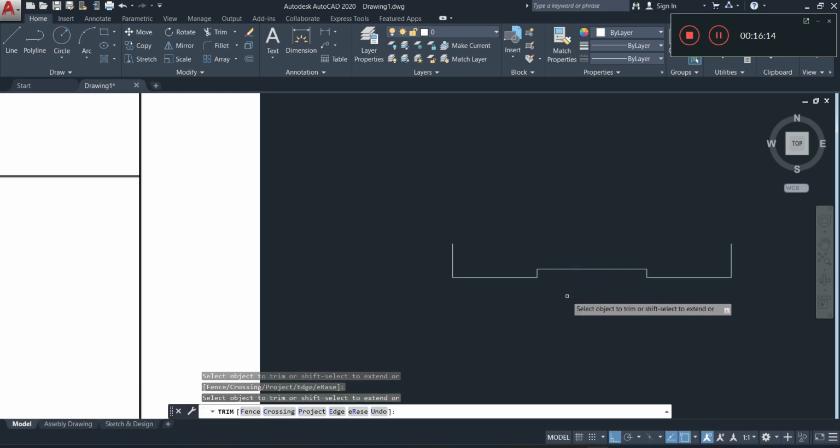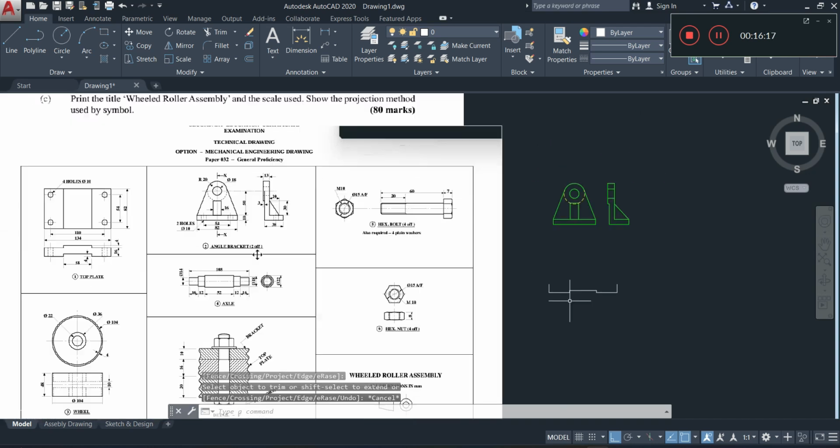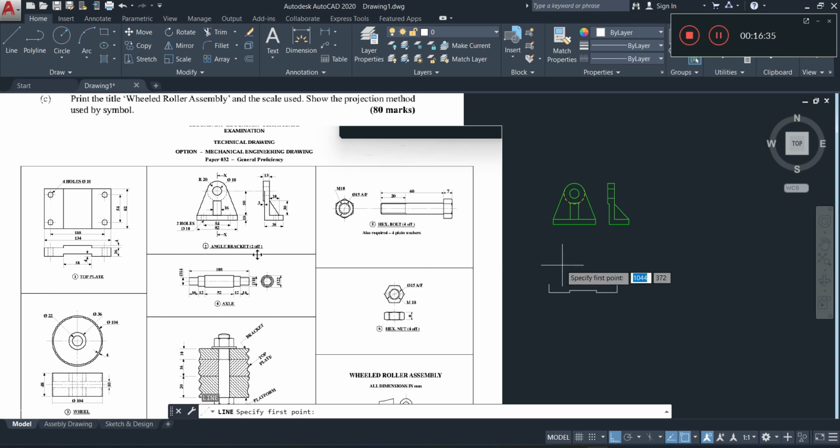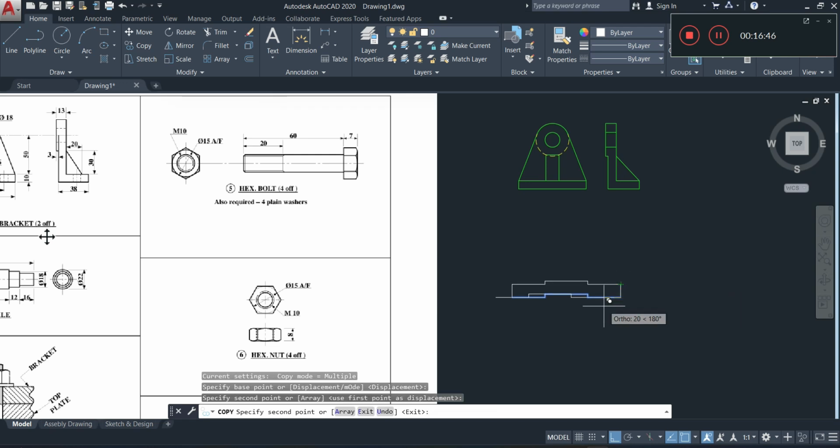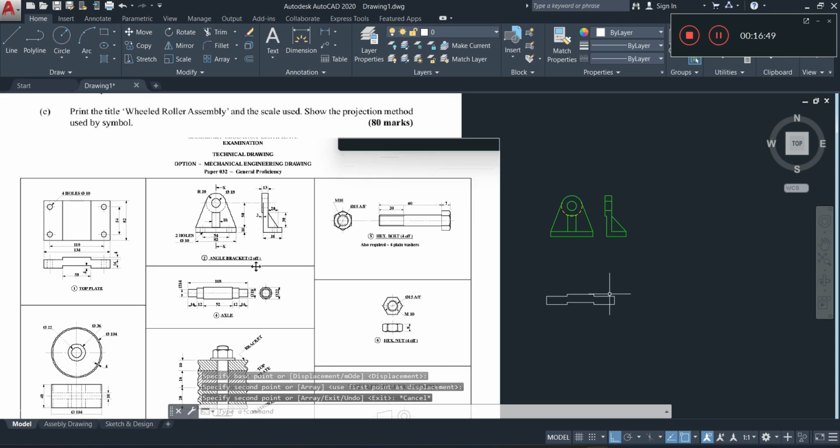That's right here. Alright, now continuing on our drawing, we can now do that little top portion up top here. Now the dimensions for that are the same as what is on the bottom, so that's what we're going to be doing, and the thickness is 4 as well. So all I'll do for that is simply grab onto this tool line here, because if you realize it's a complete replica of what is down below. So just like that, that base plate there is completed.